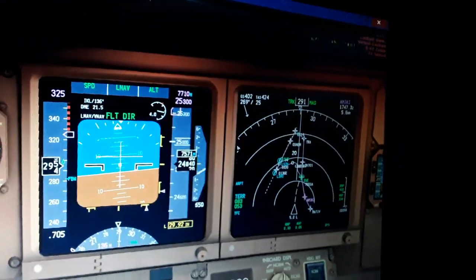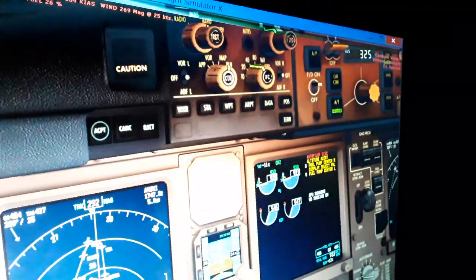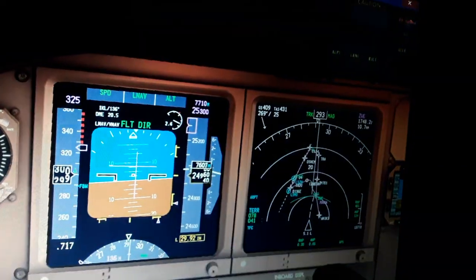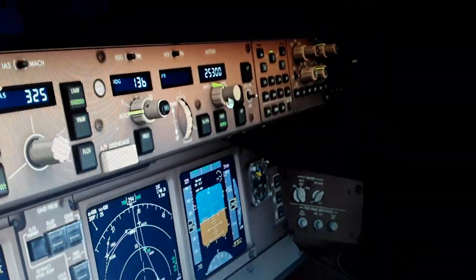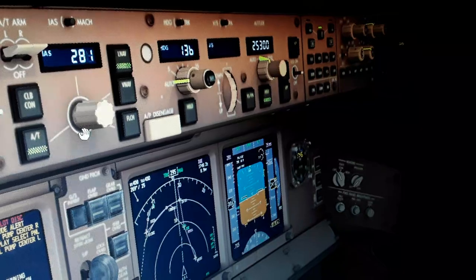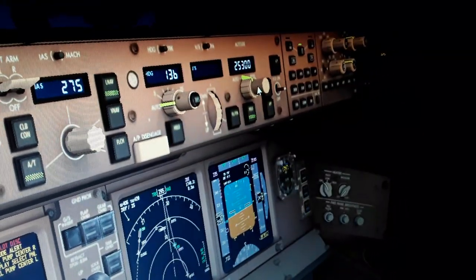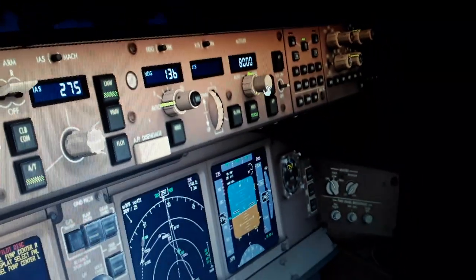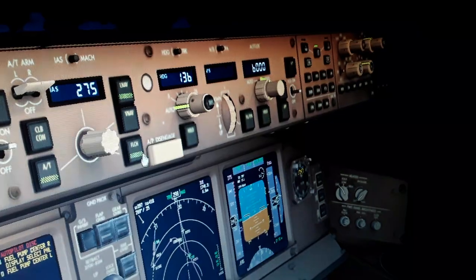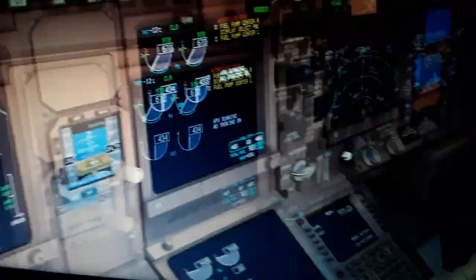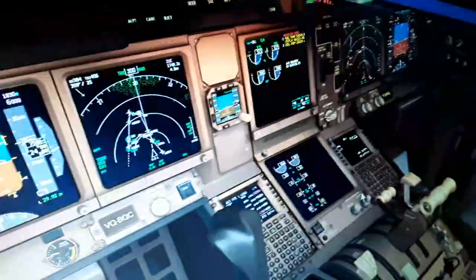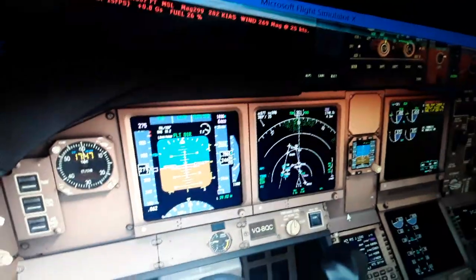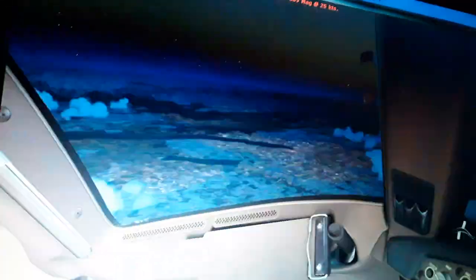We fly with about this airspeed. Now we need also to descend lower. We need to come to a descent now. Decrease the airspeed and select lower altitude for descent. Use the flight level change, and we will have the idle thrust. I'll move it by the auto throttle system, so we have a few more minutes, like 6 more minutes left to go for this flight.